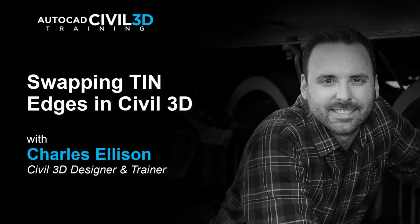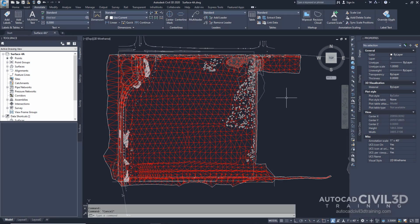Edge swapping is used to change the direction of two triangle faces in the surface to create more of an accurate surface model. For example, edges can be swapped to match the triangle edges to ridges or swales. So right now I'm in the Surface-4A drawing, which is located in the Tutorial Drawings folder.